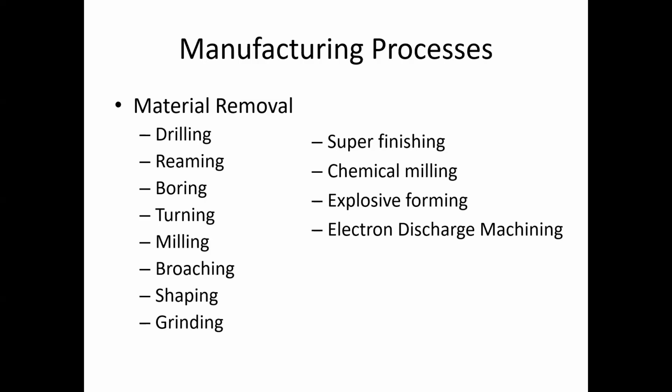Broaching. So anybody heard the term broaching? We talked about this a little bit the other day. I've heard of it before, and I used to use it at my old school, but I forgot what it was. You did some broaching? Okay, cool. So broaching is typically a process that uses a press type machine to cut keyways into a hub. This is the primary purpose. The cutting tool's got a lot of mean looking teeth, and it's just like a big arbor press that broaches through there and cuts those keyways.